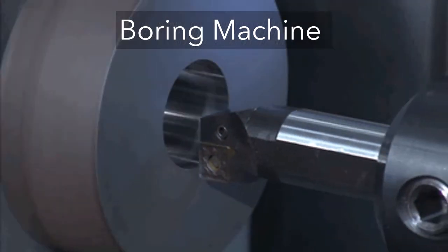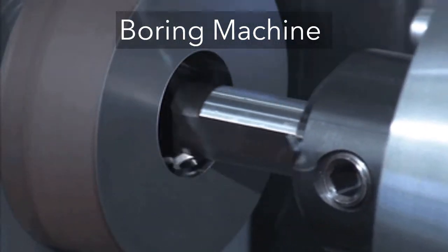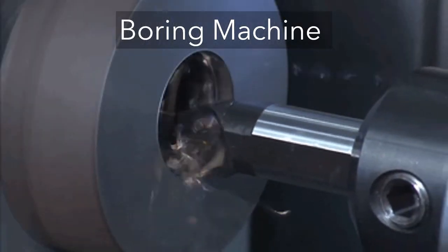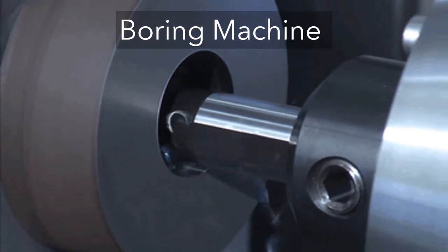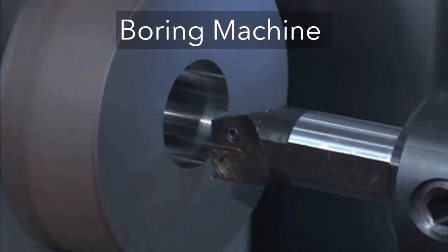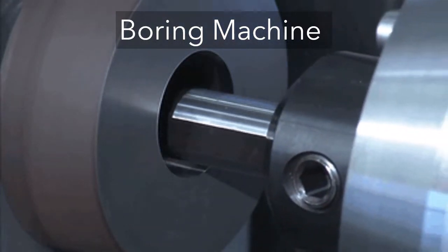Boring is similar to turning. It uses a single point tool against the rotating work part. The difference is that boring is performed on the inside diameter of an existing hole rather than the outside diameter of an existing cylinder. In effect, boring is an internal turning operation.